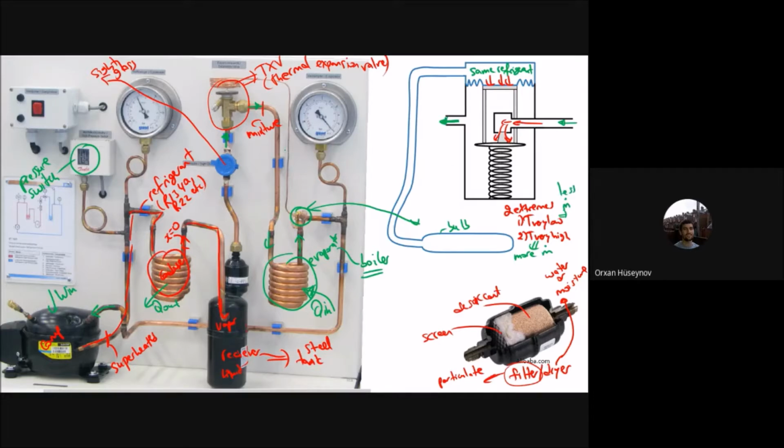So why you have these two cases is that you have to be sure that you have enough amount of the cooling process, because this part is the Q in and it is cooling. Okay. If the temperature is very high here, you need cooling. How do you supply the cooling? You supply cooling with more refrigerant. So you have more refrigerant, and therefore due to the amount of the more refrigerant, you have better cooling. And on the other extreme, you have enough amount of the cooling so that you don't want any more. So what happens is that this one blocks that mass flow rate into the system, and therefore you will have less mass flow rate. And it operates between these two extreme ranges. Okay.